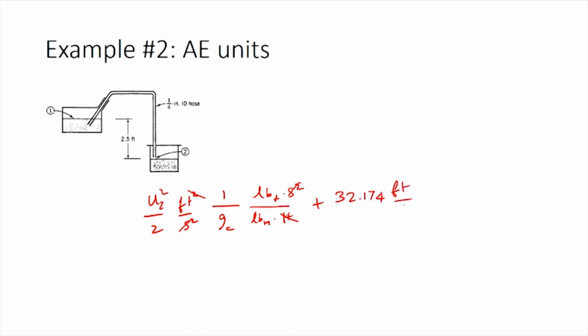The units for this would be feet per second squared times delta z, which is minus 2.5 feet, and this again divided by Gc, the units being pound force second squared divided by pound mass feet. So, you would have feet and second squared cancelled, and you would have the same units as F cap, plus F cap is equal to 0.